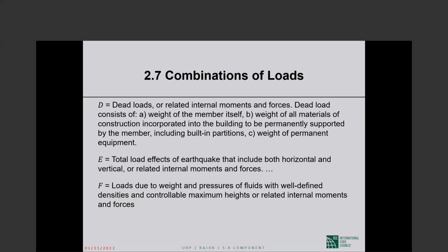And that we do by dividing by the load factor that used to be common in seismic design in the days when earthquake forces were specified at service level. That load factor was 1.4. Reciprocal of 1.4 is 0.7. So in ASD, you will typically see a load factor of 0.7 on E.